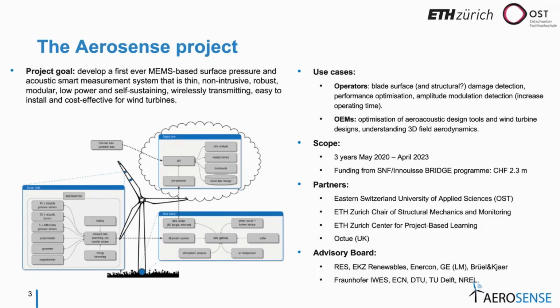And so we're hoping that we can not only use these pressure measurements, but also one other attribute of the AeroSense system: it will also do acoustic measurements. So we'd be able to use that to add a bit of information, especially for the boundary layer, so the turbulence within the boundary layer. So we could use the acoustic measurements to actually fine tune how the boundary layer behaves, right? And then we could correlate that back to the model that we're using now.